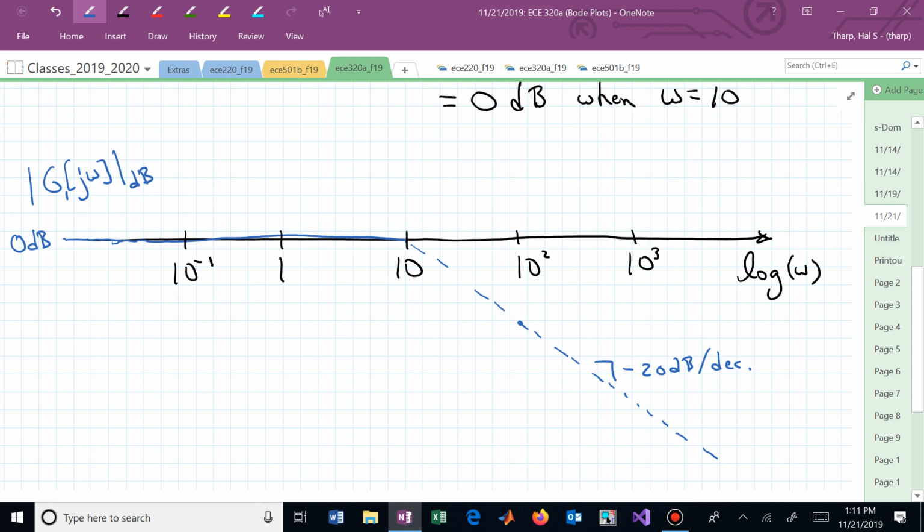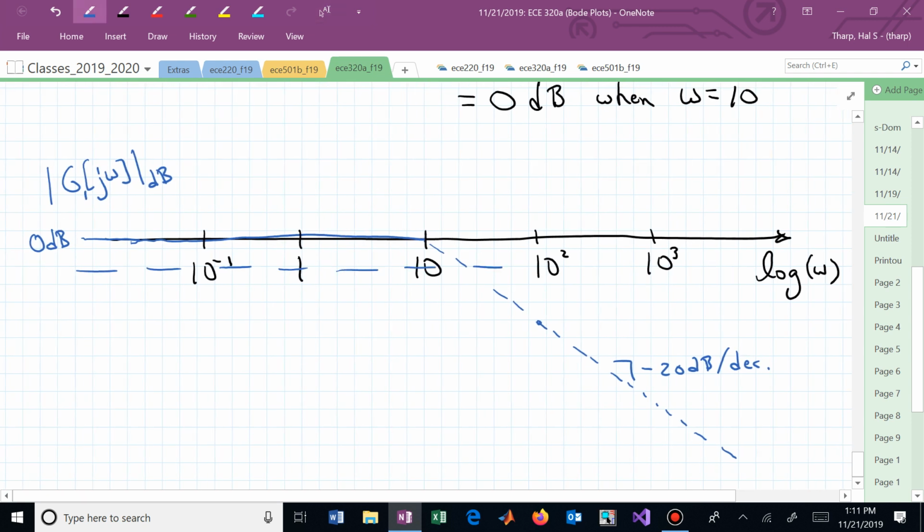And if you wanted to, you could say, well, let me draw all of these curves by themselves. Let's say this is now 6 dB. You would now just add these up point for point, because now we are sketching these in decibels, and we can add those. So now I have 0 and minus 6. I'm right there.